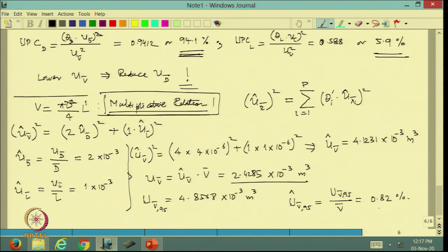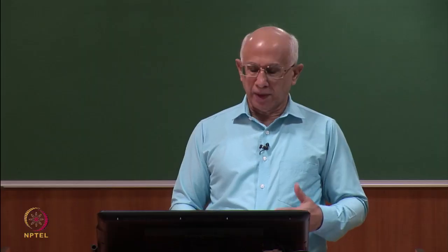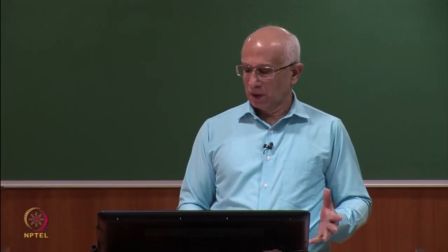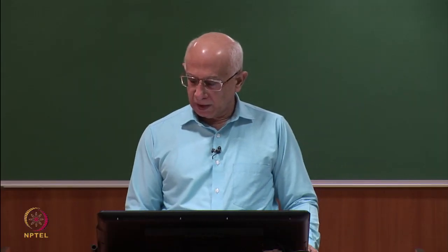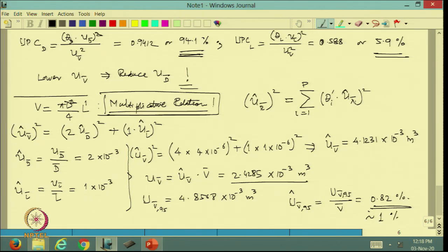So, we have a plus minus 1% uncertainty in the volume, which will also mean a plus minus 1% uncertainty in the mass, and it could be that this is a piece of wood that is being sold from somebody to somebody on a mass basis. So, both have to agree that uncertainty of the order of 1% is okay, and then you just bill them on the mean value of the volume. Otherwise, we have to end up using something else. So, that completes this example.